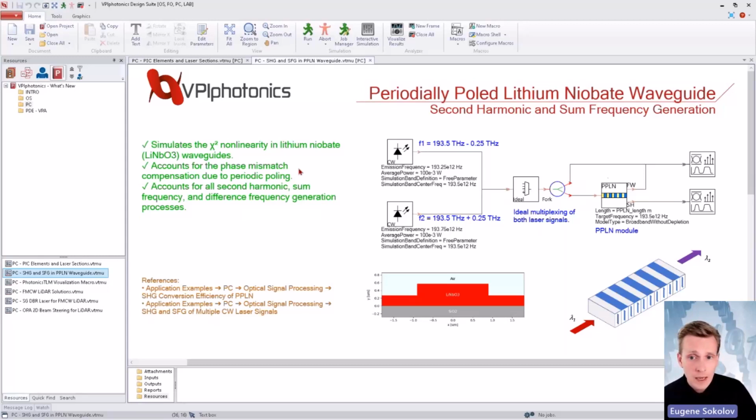One of the peculiarities about this model is that one of the main applications is generation of the second harmonic, which means that the frequency is twice as large as the original frequency. This means that we would need that large frequency bandwidth, which is for sure not applicable because the simulation would take forever. Because of that, we have the not so common two outputs of one waveguide. One is for the original frequency and another for the second harmonic.